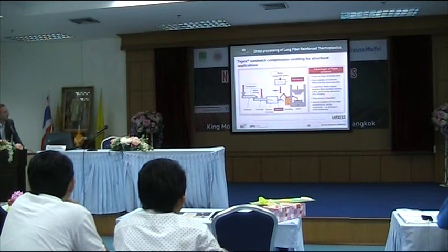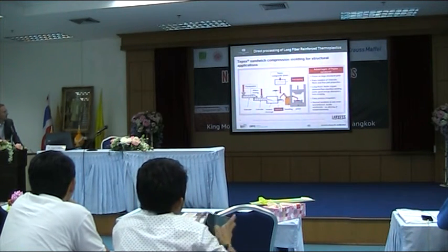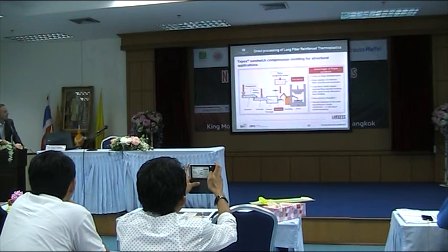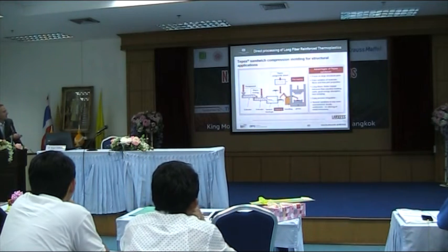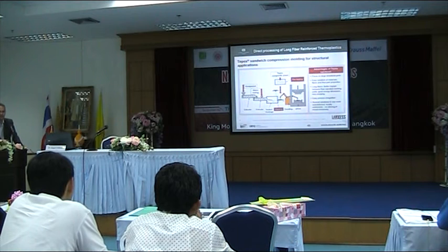So this is something, for example, from the company Lanxess, who made some parts where they applied this process for sandwich compression molding. We have parts from this compounding process, and you add some thermoplastic prepregs to make sandwich structures. Okay, you have an endless fiber reinforcement at the top and below, and between you have some short fiber reinforcement.